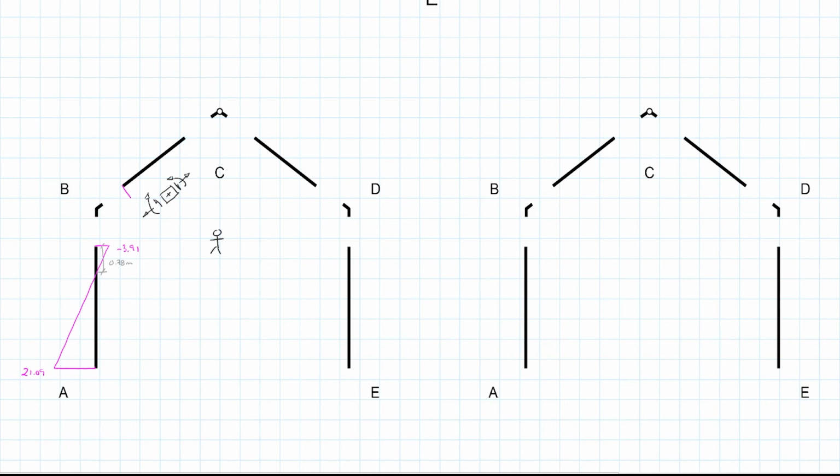We have no forces applied across the length, and so that takes us across, and then we go back up. So that's negative 8.6. You can put a negative in there. So that's a positive, that's a negative. And then again, we have to use the local coordinates when we're looking at C and D. So if I were to look at C, we said shear was 3.90. That's going up, so that should be positive for us.